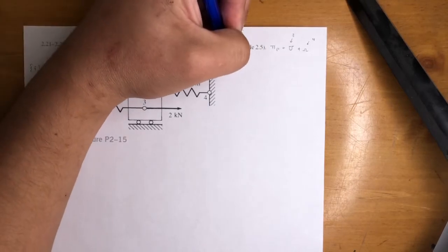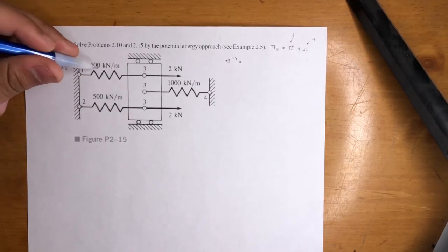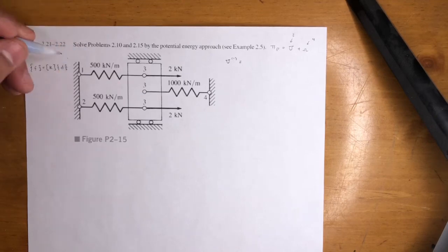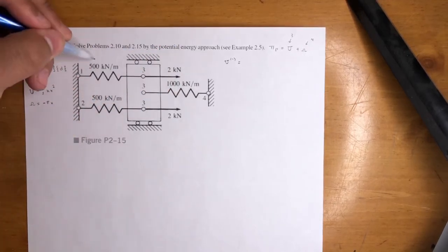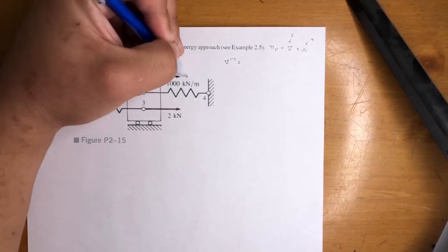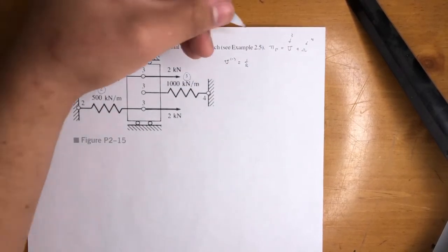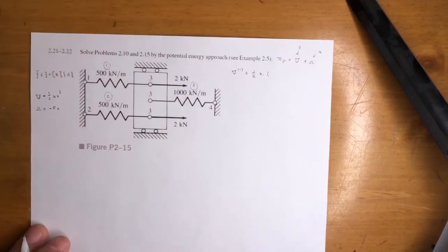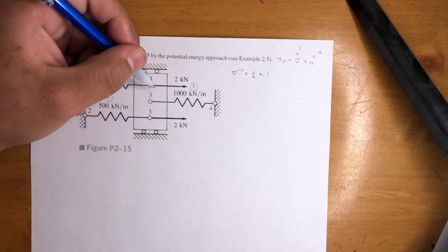And that's pretty easy, right? So the first term for U1, I'm not going to go into the theory either, but for a linear spring, we assume they're linear unless they say non-linear, but for the most part, they'll be linear. U is equal to 1/2 kx squared. There's theory behind it, but I'm not going to cover it in this video. And then for omega, that is equal to negative force times displacement. So U1 of the first spring, let's go ahead and label this 1, 2, and 3. It's 1/2, we're just using this formula, 1/2 kx squared. K, we'll put K1, and X is just the displacement after, in this example, there's 4,000 newtons going to the right at node 3.